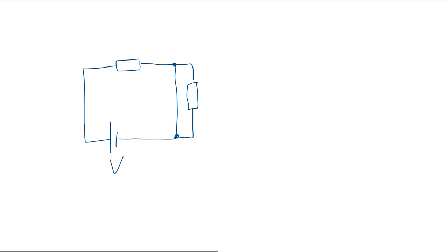If you can't visually picture how these two wires could be connected, I recommend having a quick Google at what crocodile clips are and have a look online at more complicated circuits. I have also added in a second resistor just to make the circuit a bit more complicated, but it is not important to describe these Kirchhoff laws. Remember, as I stated, current flows from the positive terminal to the negative terminal, in other words from the long vertical line to the small vertical line. Therefore, in this circuit, the current is flowing in a clockwise manner, as I've represented here with these red arrows.